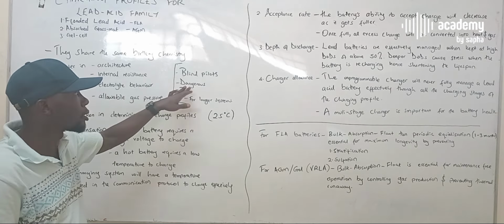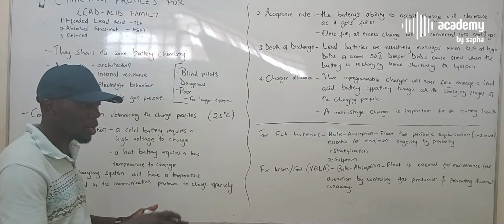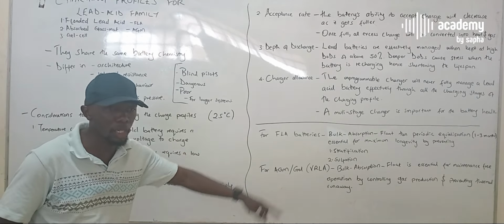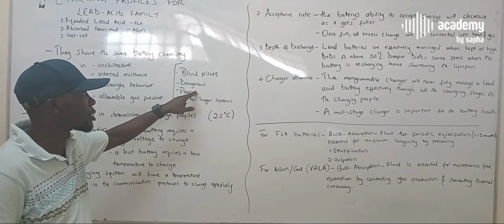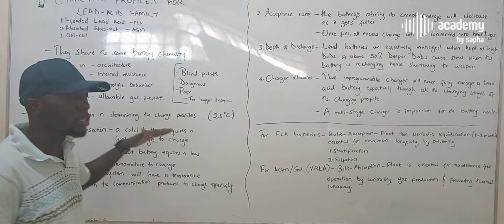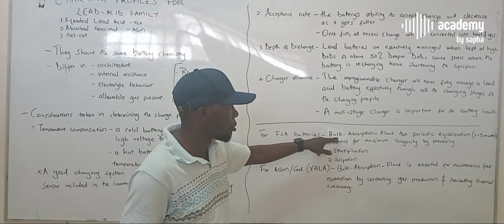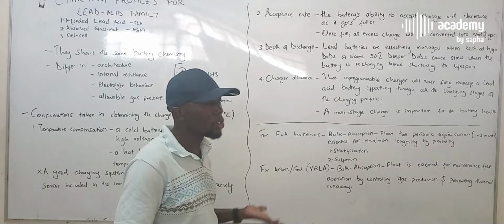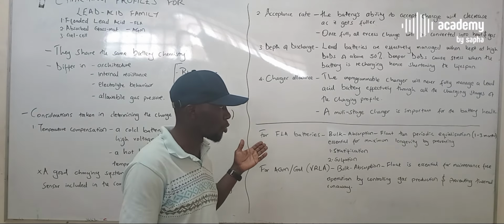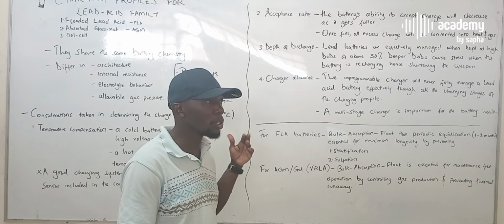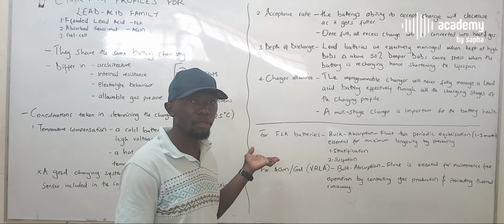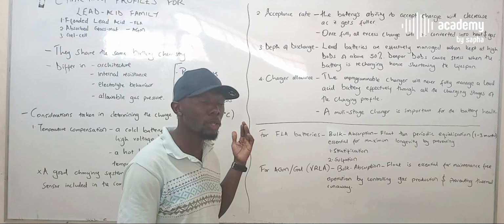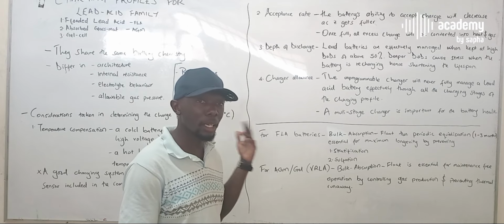If you combine a good battery bank of whichever type, either FLA or AGM or gel, with a charge controller that cannot communicate and ensure that these batteries go through these charging stages effectively, even if a battery has been marketed to go for at least 3,000 charge cycles, you'll realize that it will not even hit probably 2,500, while operating with both SOC and SOH still at 100%.